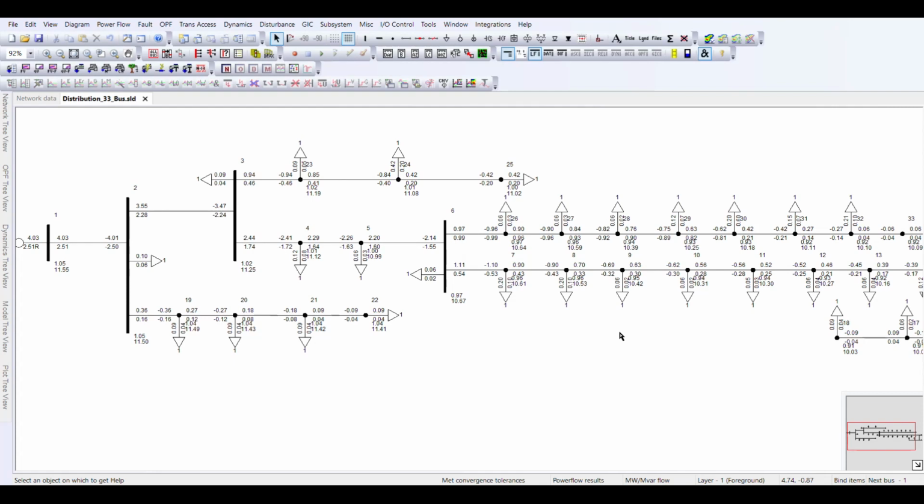I cannot attach more PV or wind or distributed generation into this particular system, because one of my indicators, one of my quantities, one of my parameters has been violated. So the methodology we are going to follow is something like this. We are going to attach distributed generation as a negative load, because we just want to figure out how much generation is possible without going into the details of how much reactive power we are going to get, because we are doing some basic analysis.